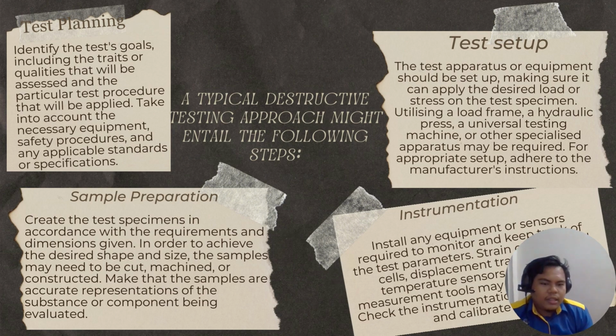Instrument installation. Install any equipment or sensors required to monitor and keep track of the test parameters. Strain gauges, load cells, displacement and temperature sensors, and other measurement tools may be used. Check the instrument's correctness and capability.